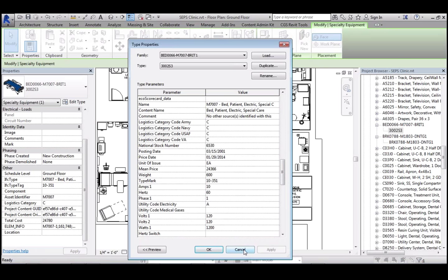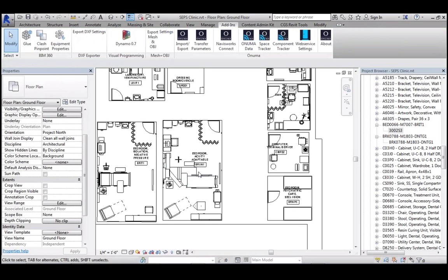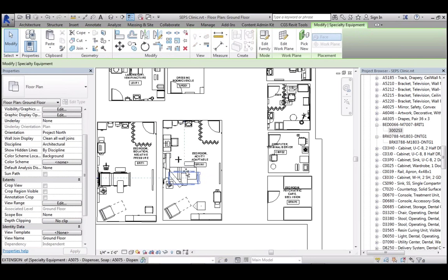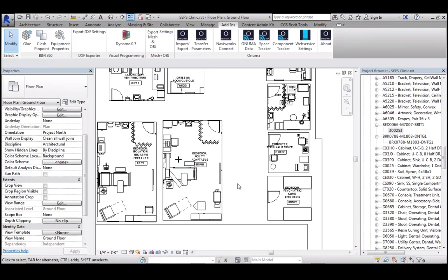This could be, as I said before, special objects that the design team is using, or it could be manufacturer-specific objects. And I could now delete this bed, but I keep track. So I have now the correct bed in here, but I keep track of the correct information in this model. So I can always go back and create delta comparisons with the original project. I can do this even in here.